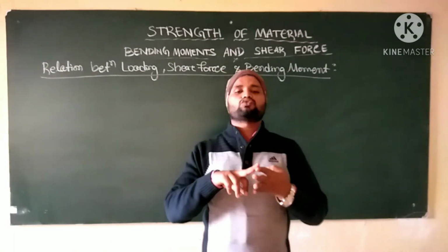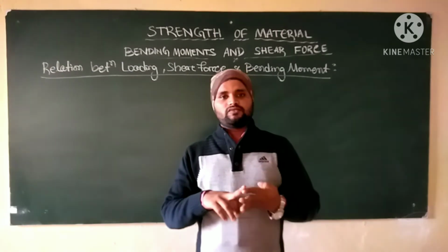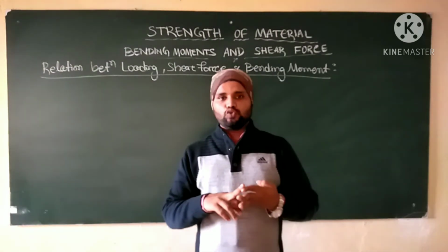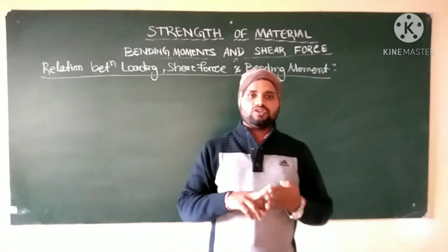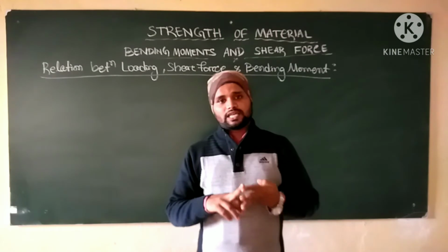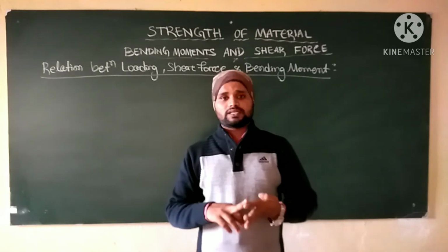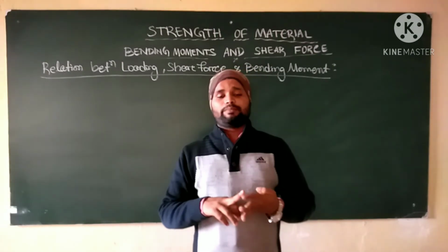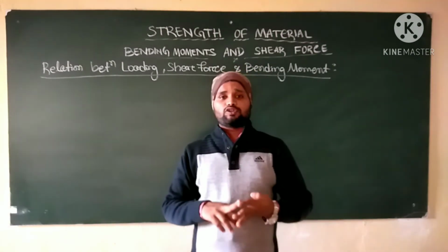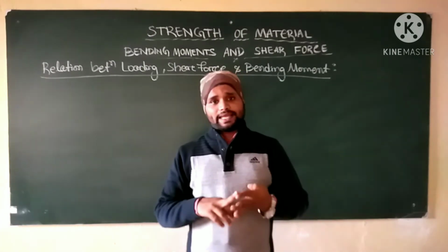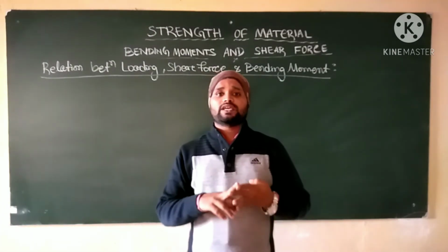Then the fourth one, the last one, if there is a uniformly varying load between 2 points, then the shear force changes according to a parabolic curve, but the bending moment changes according to cubic law. That is, the bending moment line will be a cubic curve.